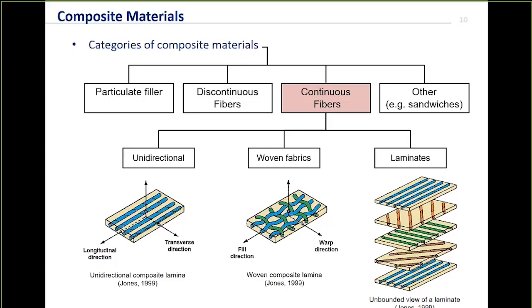So you can do this by weaving it, which has the advantage that it also looks pretty, or by creating a laminate with layers with different orientations. So these types of material are much stronger than the chopped fibre composites, but you're also a bit more restricted. They're not so easy to shape, and they're more expensive to manufacture in terms of the time to assemble and cure each part. They normally have thermosetting matrices.